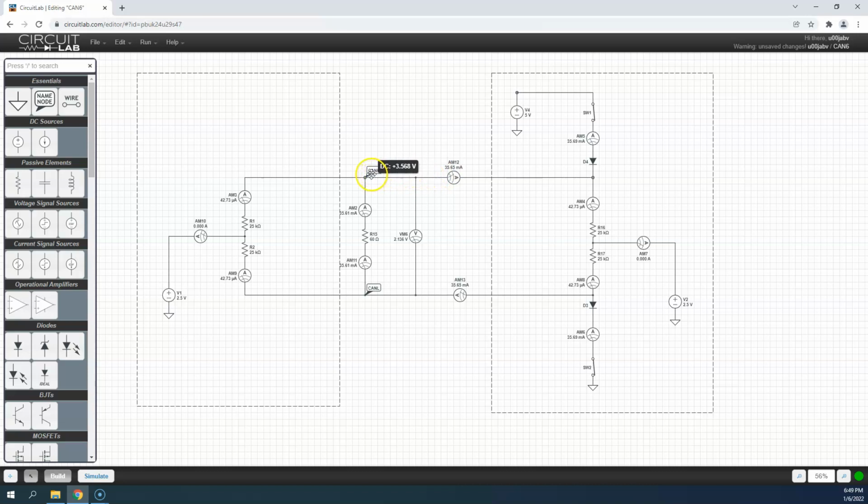We are going to go through, as we can see here, the majority of it is going to go through the termination. And I've got it modeled as 60 ohms. If this were 120, we'd have half of it going one way, half the other way, and it would join back up. But for what we care about in a model, it's the same, it doesn't matter.